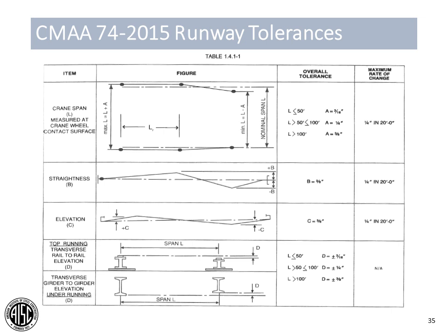Here we've got the criteria for, or tolerances for, the bridge span itself, or the crane span. We have anywhere from 3/16 to 3/8 of an inch, depending on the overall span of the bridge itself. Straightness tolerances, so this would be the lateral alignment of your runway itself, 3/8 of an inch. Total deflection or out of tolerance is allowed, and a 1/4 inch rate of change in 20 feet is the allowable angular deflection or misalignment of the runway systems.